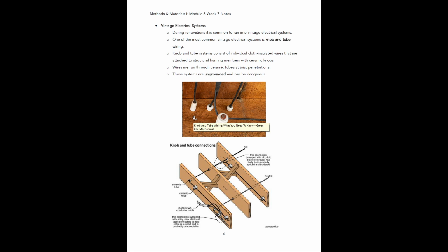Now these are used in a lot of, like I said, historical houses from the early 1900s, late 1800s. They're in my house. And a lot of houses today still use them. I mean, it's not still being installed, but a lot of these old houses that haven't had their wiring updated are still running on them. Now, they tend to be ungrounded, and we're going to talk a little bit more about ungrounded and what that means later on. But that can cause them to be dangerous in a lot of cases.